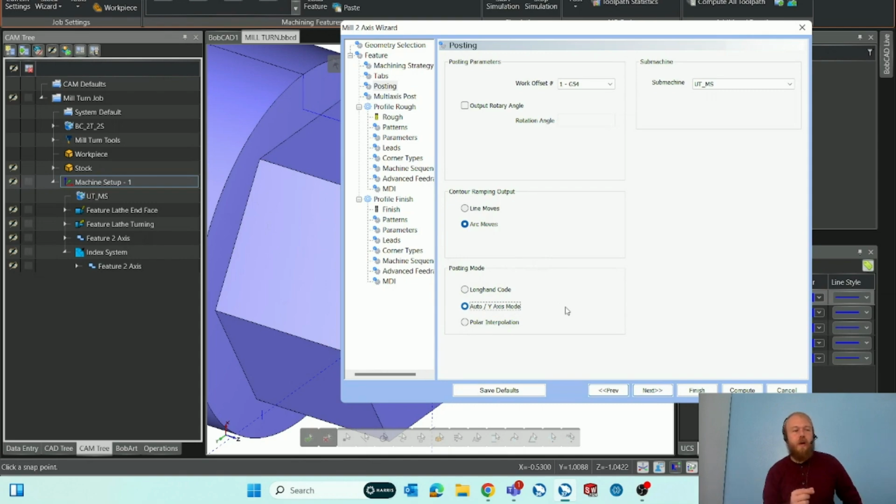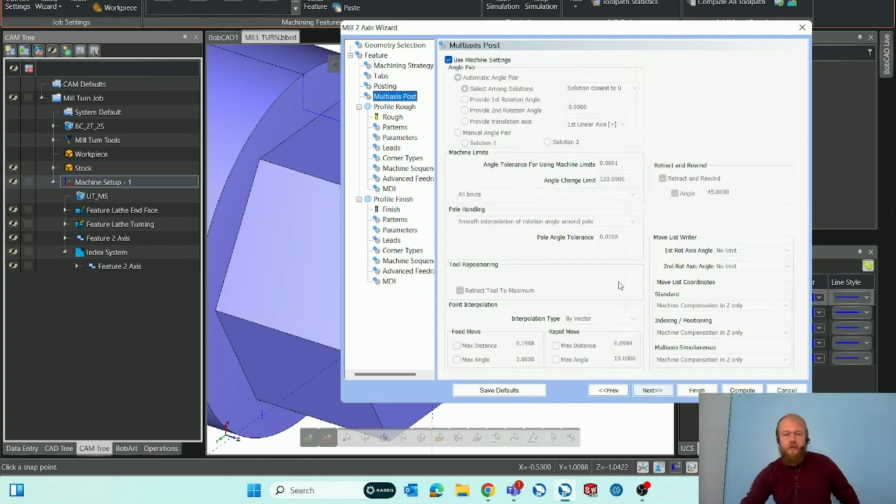The tool is going to move back and forth in X, positive and negative, to be able to give you the profile around the hex without having to move in X and Y. And I'll double check that in simulation, make sure that's correct there.